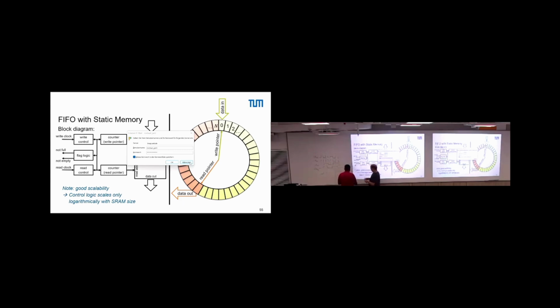So effectively, what we have is one signal that goes out. The full signal would look like this: at some point we are full, and then if we read, we go down. The not full signal is just the same, it's one and goes down. You would not wire twice. You have one of them, and then you evaluate accordingly. So, in that sense, you have only one of them.